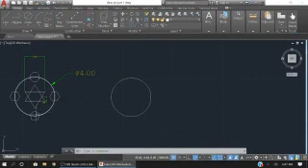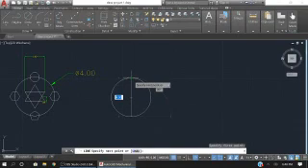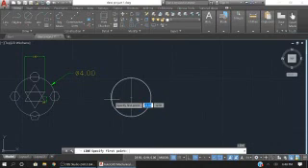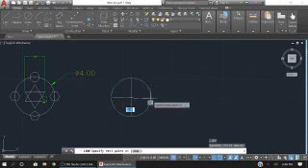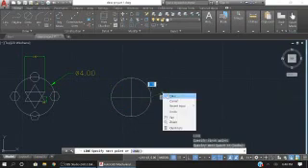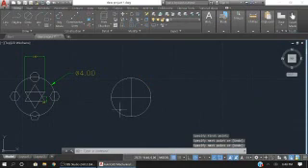Now my next thing is I want to make my construction line that's going crisscross. So I'm gonna come here. I'm using quadrant snapping. Okay, so I'm gonna press escape and I'm gonna press enter back again. It's a shortcut key to get back to a sketch entity that you were in previously.